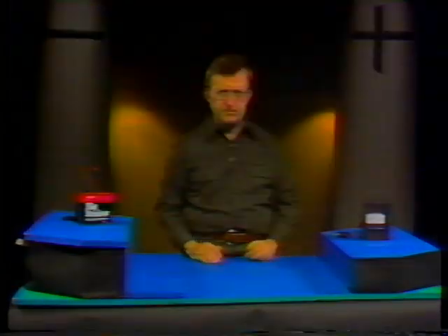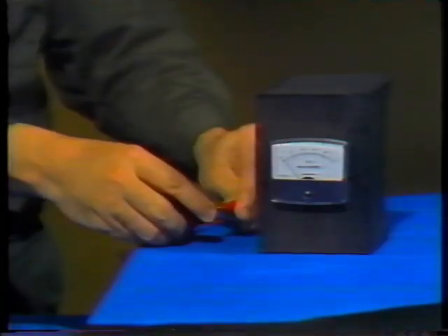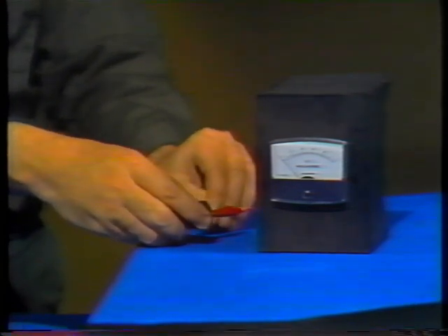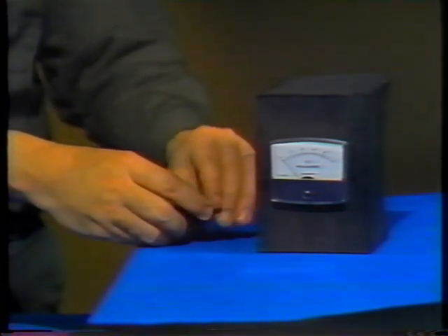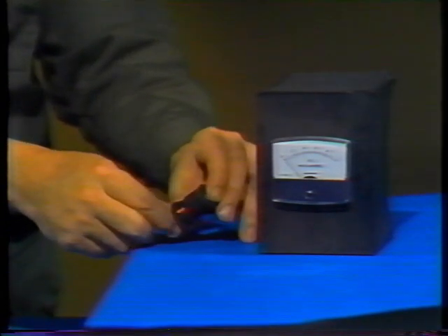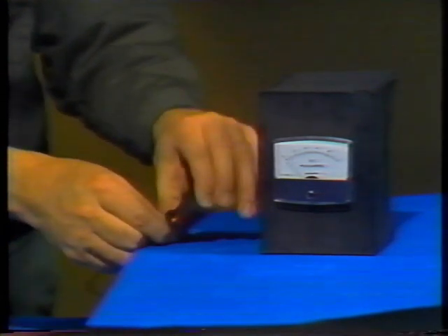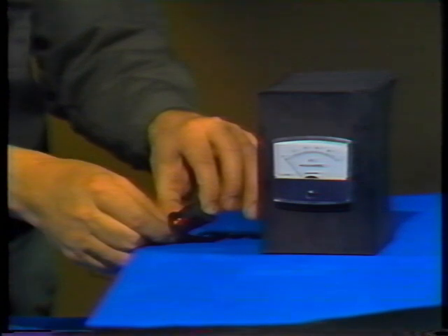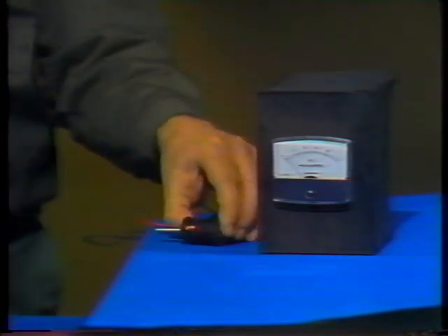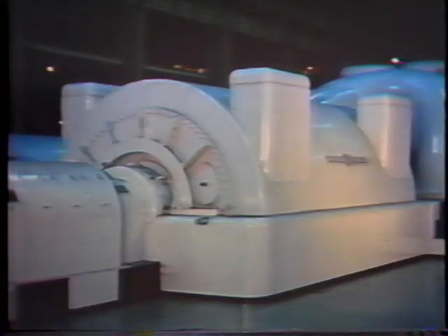Now, the motion of the magnet moving through the wire wrapped around the spool is what induces the voltage that causes current to flow through the wire. Next, I'm going to hook these two wires up to the spool. Any reading on the meter now? No. But as soon as I move the magnet, the needle jumps, indicating a current. If I move the spool, same thing happens. We can produce voltage by passing a conductor through a magnetic field. Now, magnetism has a lot to do with how your plant operates. You've got magnetism working for you in generators, in motors, and in relays that keep the equipment going.